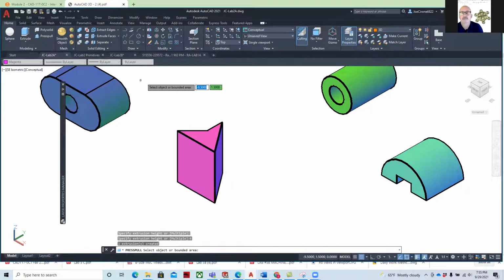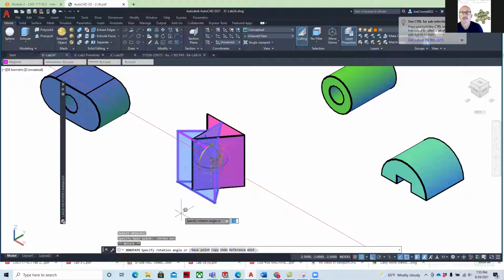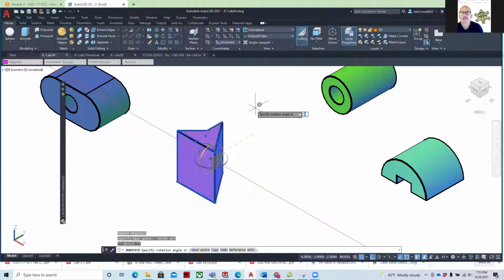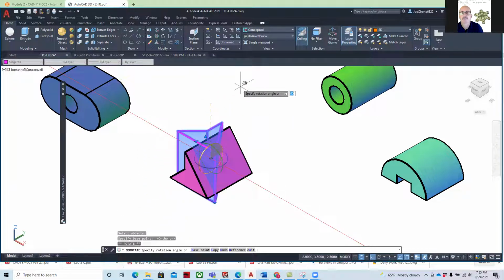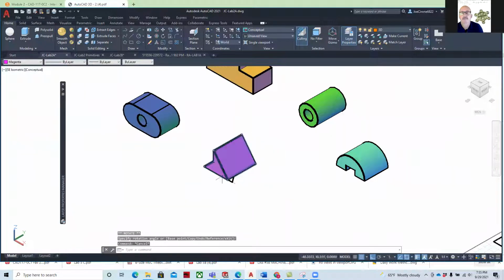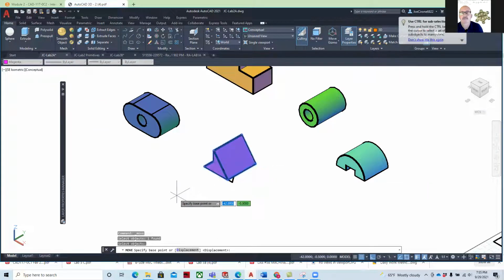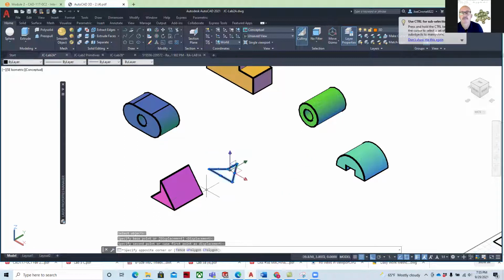And then we'll 3D rotate that. Turn on our ortho. Select our axes. Sometimes you have to exaggerate the amount, so you may have to zoom back a little bit. Move it off of our sketch geometry. Erase our sketch.